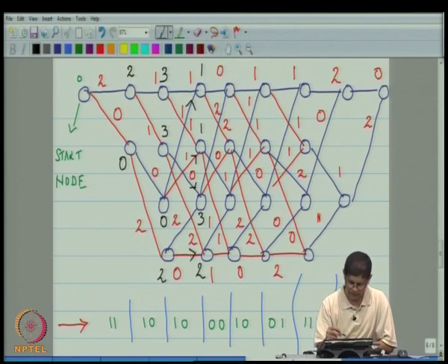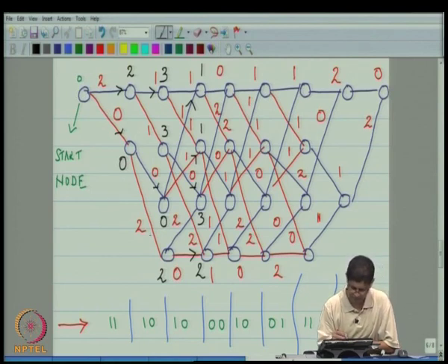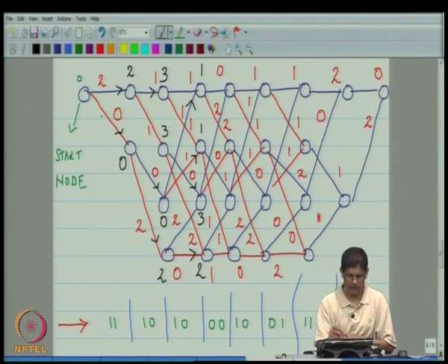And then just to be consistent, let us also put an arrow in the previous paths, although there was no selection to be made there, that was only because there was only one incoming edge to each of the nodes. So, now at each node, if you trace back along the path, you see the path that is most likely, given what you have seen thus far, to be the code word in terms of Hamming distance.